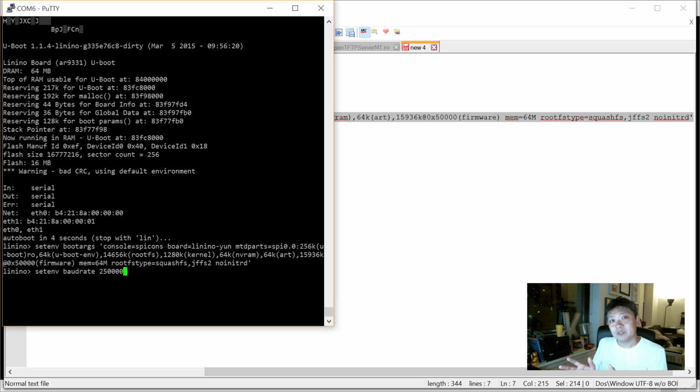The reason we're doing this is because when the thing originally boots up, the baud rate is at like 115200, or I forget what the number is, but it's basically at a baud rate that's slower than the 250,000. So that's why we see the gibberish in the first screen, then it goes to normal characters, but when you switch the mode, you can see it. So we're going to try to set the default baud rate to 250,000. When we do it, it's going to say switch baud rate to 250,000 and hit enter. So we'll do the ~2, it says set speed, hit enter, and we're back to normal. Alright, so we are now going to reset again.